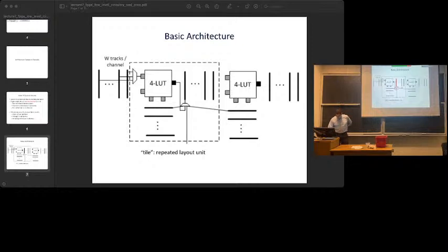This lookup table can drive into this multiplexer. Also, these other routing wires can drive into it. That allows me to select how I'm connecting things, right? I can connect my outputs into the routing channels. I can connect wires to each other so I can go long distances. And then at the other end of my route, I can get into the logic block by going through this mux. Okay, so does it make sense?